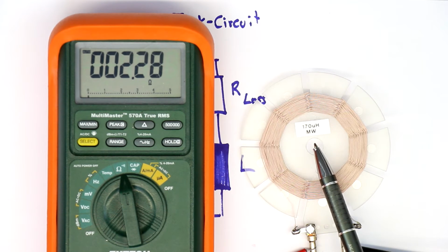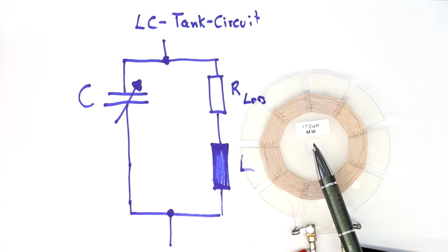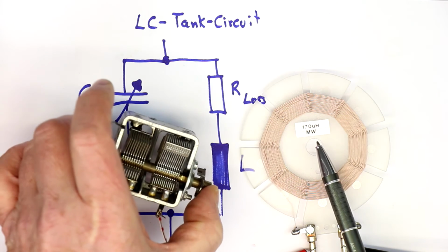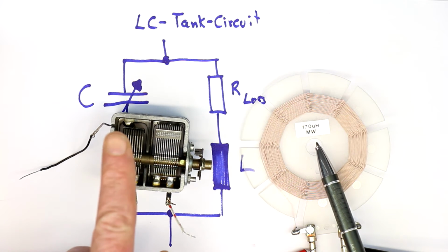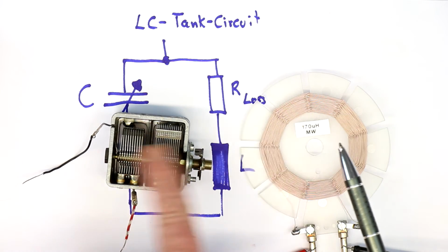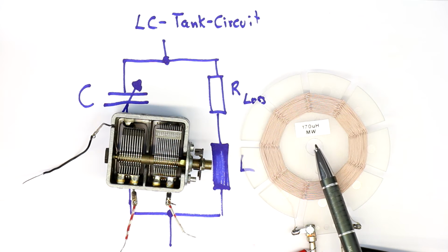And the Q factor of this coil is determined as somewhere around 100, at 1 megahertz frequency. So we will have to connect the reception coil with a variable capacitor, and we'll tune the capacitor so that the resonant frequency is exactly 1 megahertz, and that will be our simulation.